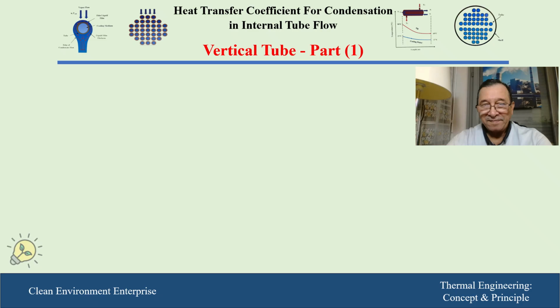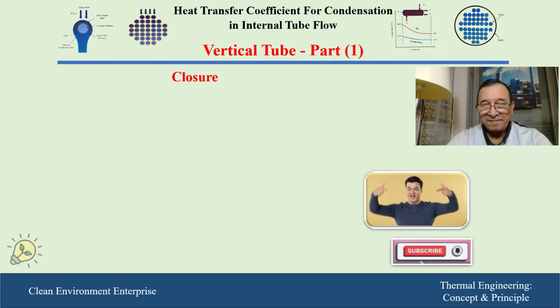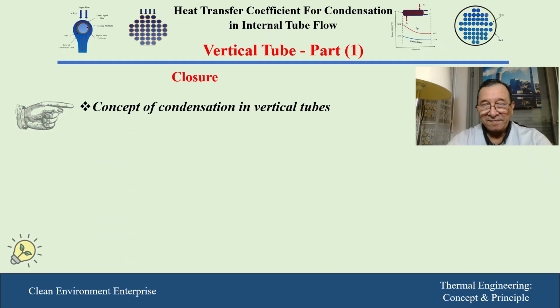Now we have arrived at the final section of this episode. We passed through the concept of condensation in vertical tubes, and we described the regions of the flow: desuperheating, condensation zone, and finally we may have a subcooling zone.